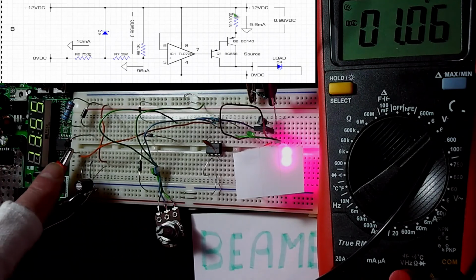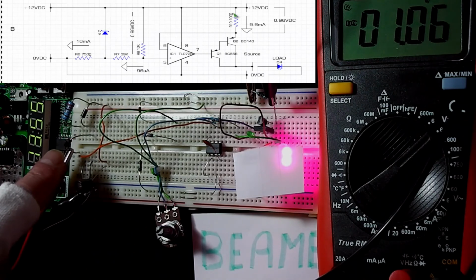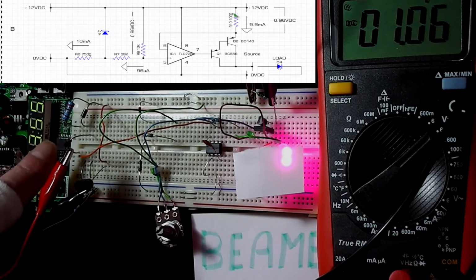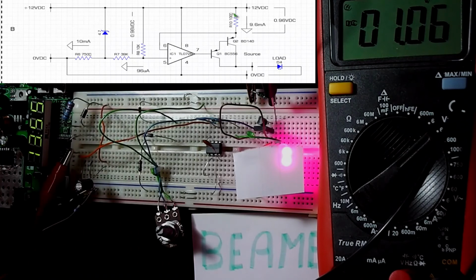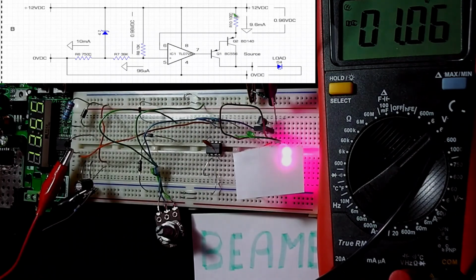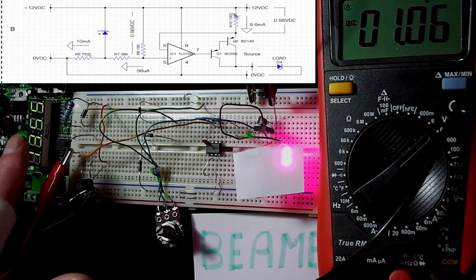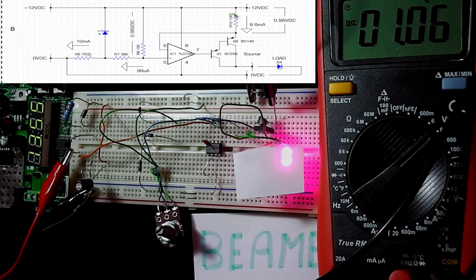Hopefully you can see now that I've added a second diode in series. These diodes would have to be rated well above the maximum current that you would want to draw through Q2. So they would need to be maybe 4 or 5 amp diodes, but that is producing 1.5 volts drop, and I've got the positive side of the op-amp IC1 pin 8 through to the anode of the first diode, therefore lifting it above 1.5 volts.